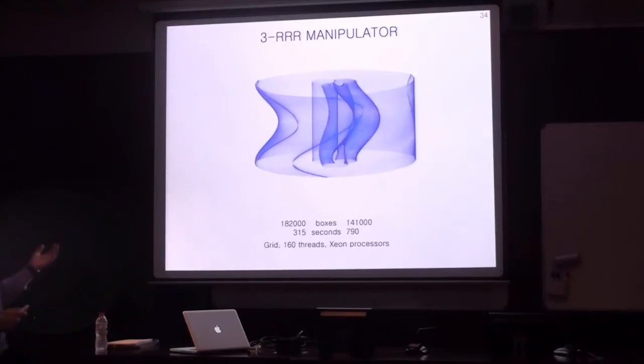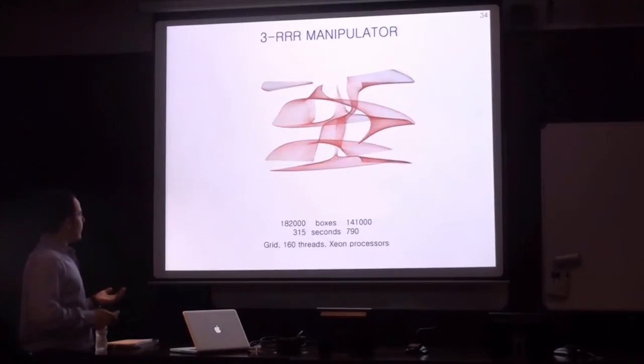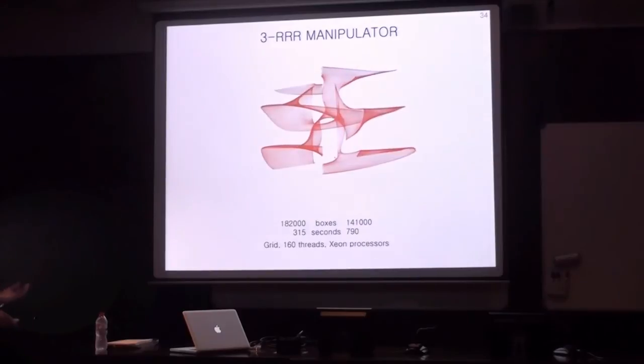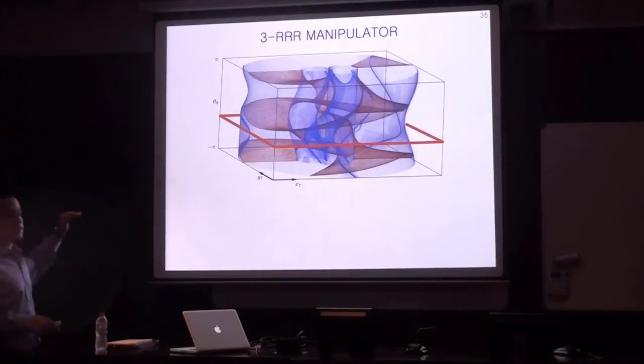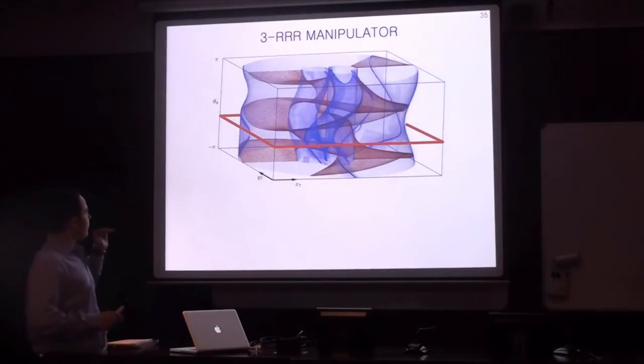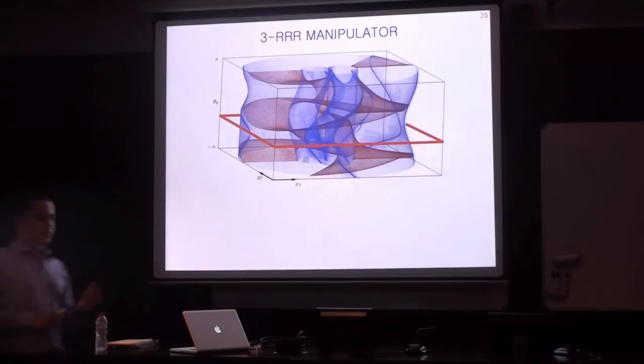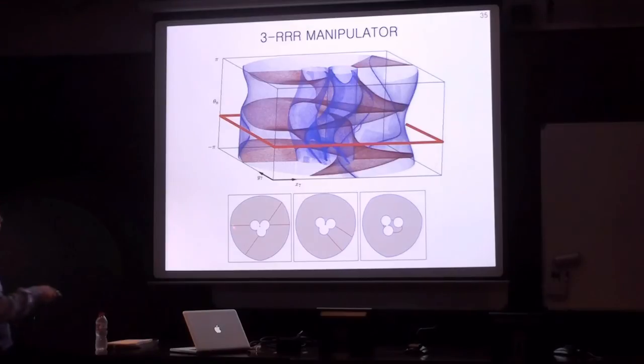These surfaces seem to be very complicated, but it was shown by Bonnet and Gosselin that the constant orientation slices of these surfaces contain only conic curves for the forward singularities. So if we compute these slices, we can see that only pairs of lines, parabolas, or ellipses appear.